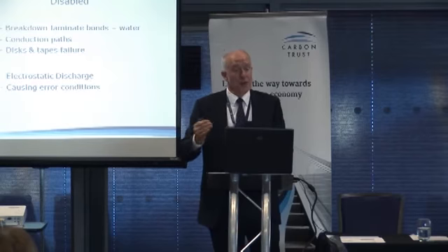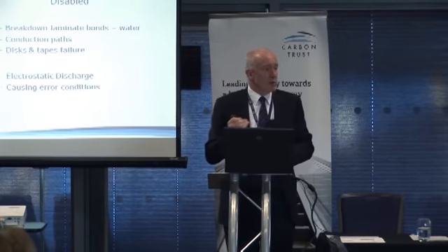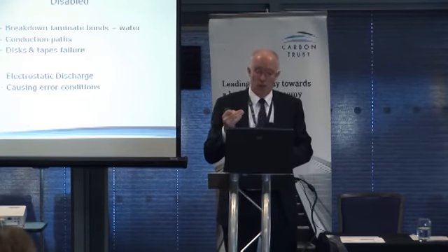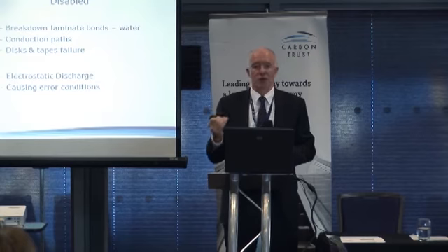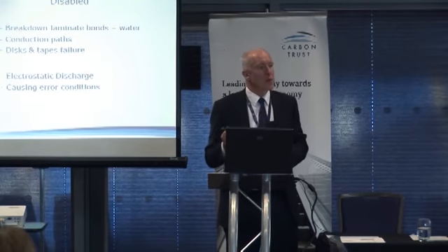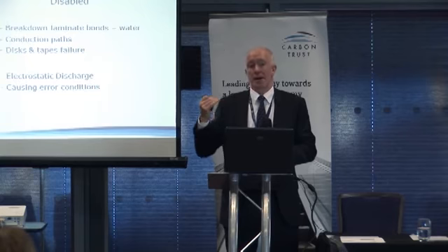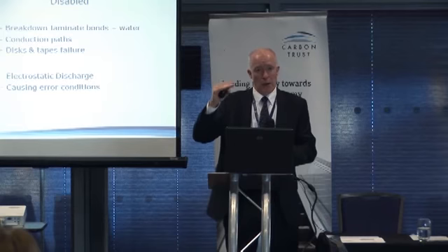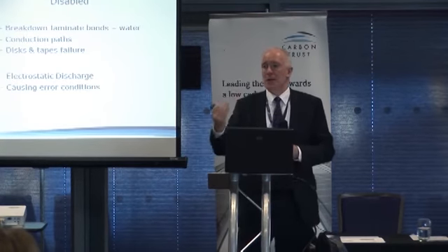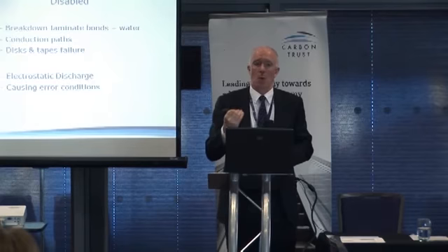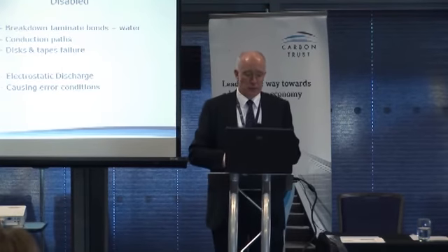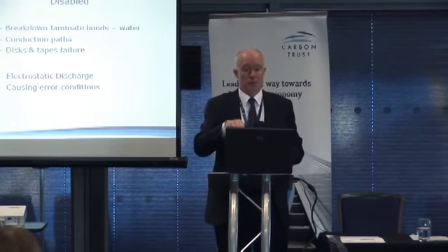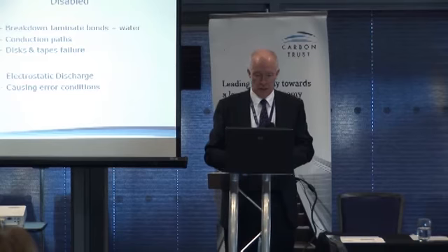On the other end of the scale, very low humidity can cause electrostatic discharge, and again that can damage your chips. So the time for low relative humidity is when it's freezing cold outside. When we're sub-zero, the air is cold and has no moisture in it. It's dropped out onto the floor as ice and precipitated. So when you've got dry, cold air outside in the depths of the winter coming in, it's going to be very, very dry in a warmer environment, and therefore you're going to have problems with electrostatic discharge. So at certain times of the year, be aware: if you are finding problems on your computer systems, could it be caused by humidity issues?